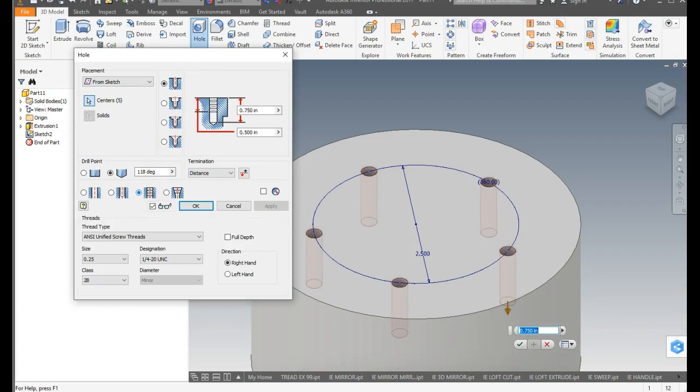I'm going to point this out right now. When you click on the threaded portion the first time, it's going to probably take about 2 minutes to build the thread database in the background. After that, it will work very quickly. So the first time you click on this, it's going to take a minute or two for it to load up. Notice how you can choose different kinds of threads and things right here. I'm really not changing the thread any today on this. I'll be changing the size later, but I just wanted to point out when you click on this, expect it to kind of hang up.